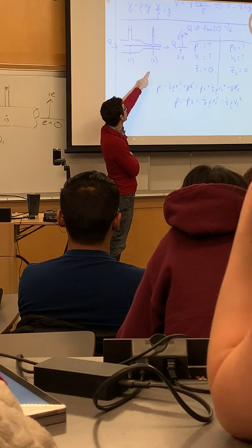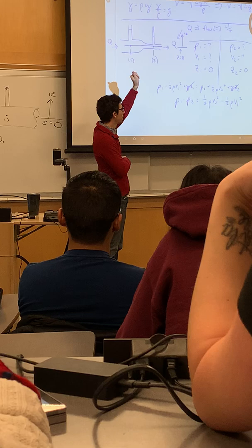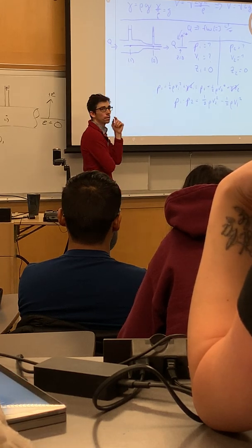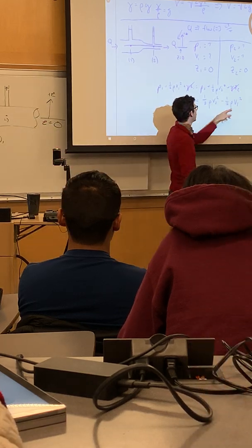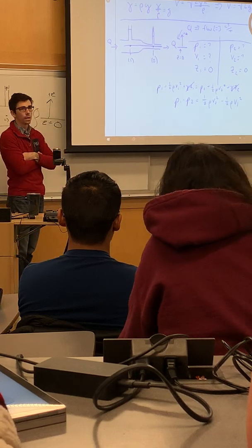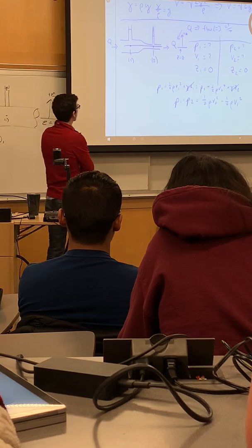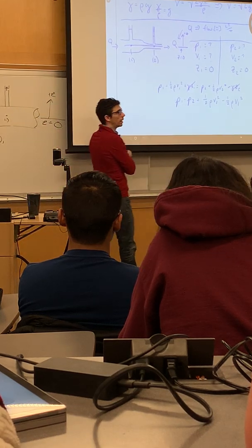To move Q through a smaller area, we have to increase the velocity at 2, right? So that means V2 is greater than V1. And if V2 is greater than V1, is the right-hand side of this equation positive or negative? Positive, right? So mathematically, we can prove that the static pressure difference has to be positive. So that's kind of cool.